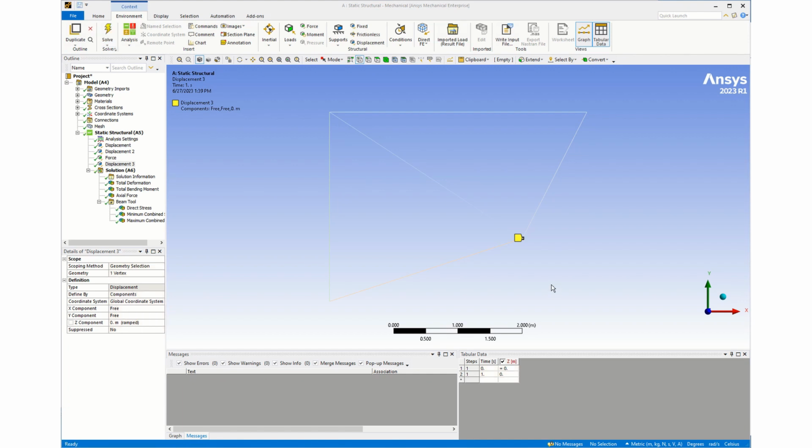So you can see it solved really quick, and I have a bunch of green arrows. Sometimes we get frustrated thinking, hey, ANSYS is not working right, ANSYS is telling me this and I've got my model right, but ANSYS is understanding the model, and we need to make sure that the model's doing exactly what we think it is. And so when you get that small pivot error, it's usually because your model is unconstrained.